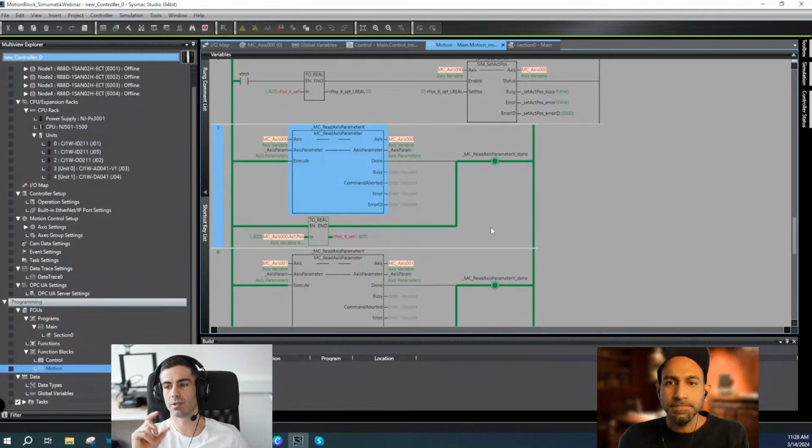There is something we need to fix in the driver because we didn't consider exchanging LReal variables, and we are going to add that feature as well. So it was limited to just Real. But it's okay. In the PLC it's much easier to convert, I believe.